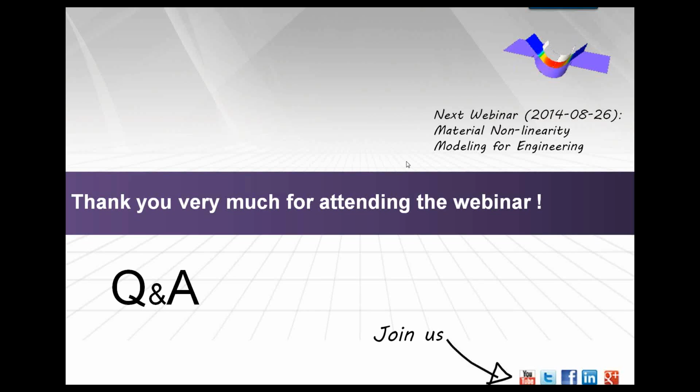Okay, I have a question about the special mass. You don't have to apply the hydrostatic mass automatically to all the nodes. You can also do it directly in the properties of the mesh on the plates. You can add this additional mass to the element. And you can also create it on all the nodes if you want or if you need to do that. So you have the choice.